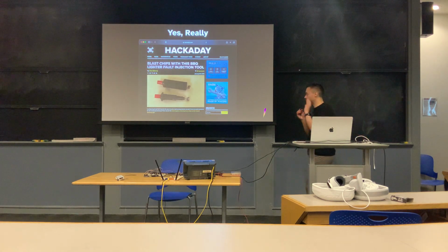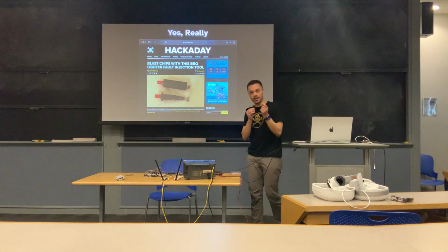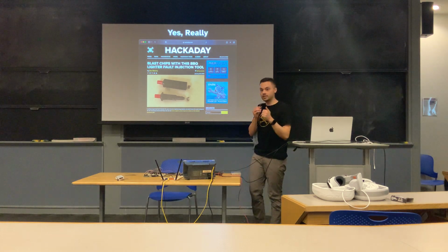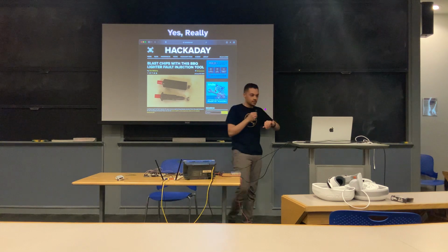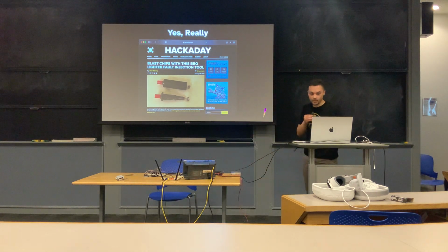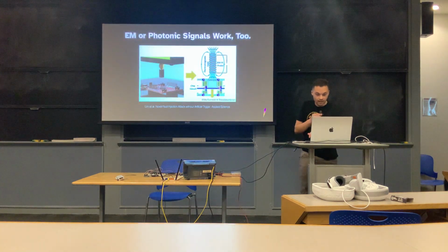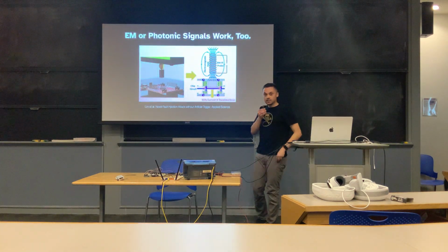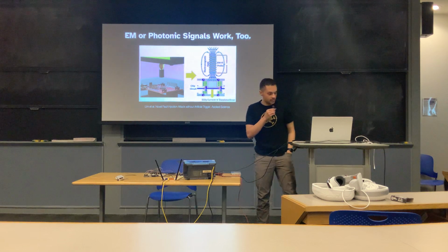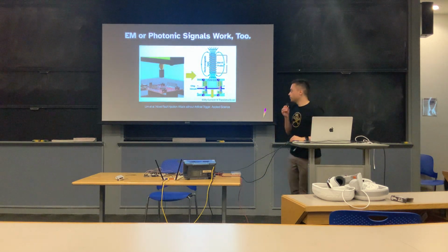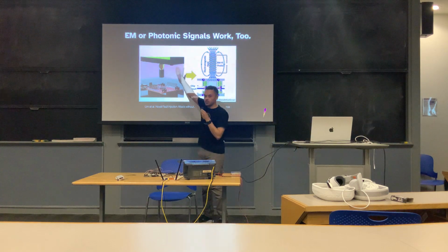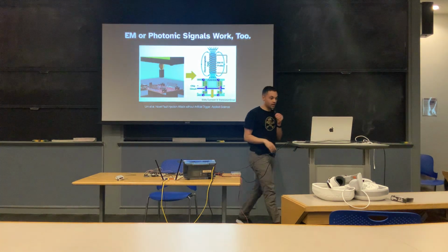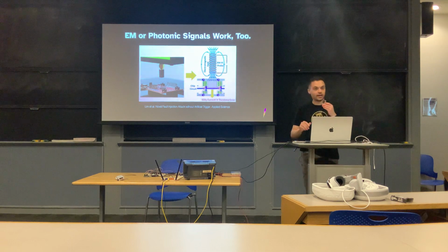If you take the piezoelectric crystal out of the grill lighter and you send it a voltage pulse, it will induce an EMF into the chip that's able to induce faults. So it really does work. You can try this if you want. Yeah, so barbecue lighter, fault injection. You can also use more advanced electromagnetic signals or photonic signals as well. So here's an image from an applied science article showing some more examples of fault injections. You can have really cool benchtop setups where you have this precise ability to inject. If you want to know more about that, talk to Vincent. His lab used to do a lot of that.